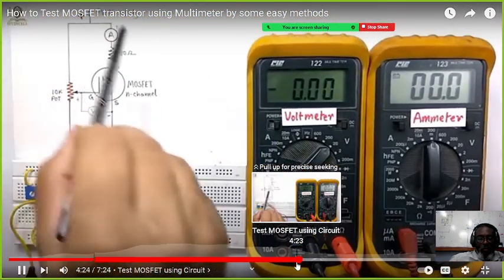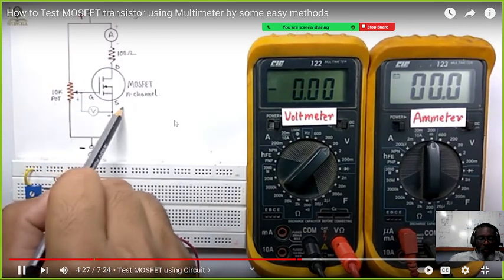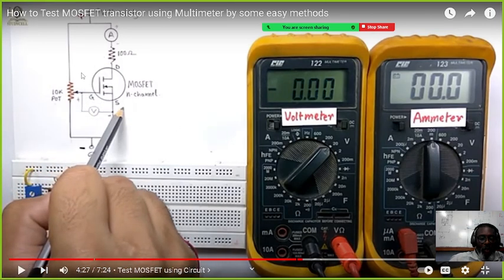If you want to take the test further, we can use this circuit to test a MOSFET. This was the circuit that they built. They tested to the end, and they set up two meters like this, a voltmeter and an ammeter. They put the ammeter right here and the voltmeter right down here, and they write down everything they get. They even put on the VGS, which is the threshold voltage, to find out what voltage. After they turn the potentiometer, after a while the RDS breaks down and the RDS resistance gets so small that the MOSFET turns on. The voltage that turns it on is known as the threshold voltage.